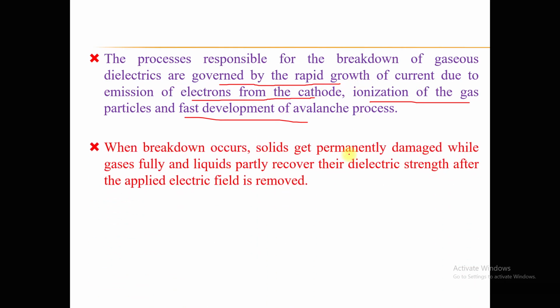Whereas in case of the solid dielectric materials, when the breakdown takes place, the solid gets permanently damaged, whereas gases fully and liquids partly recover the dielectric strength when the electric field is removed.